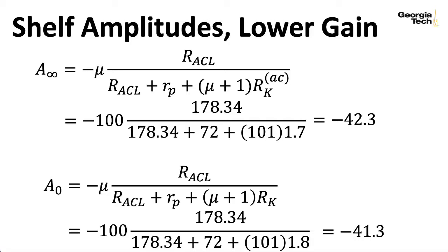So that capacitor is not very exciting from a frequency point of view, both from the standpoint of the relative height of the shelves and from the standpoint of the fact that that zero was at 3.3 hertz. Although to make that statement about it not being very interesting concrete, if I had a case where these gains were different, I would also have to really compute the pole frequency. I'll talk about that later.